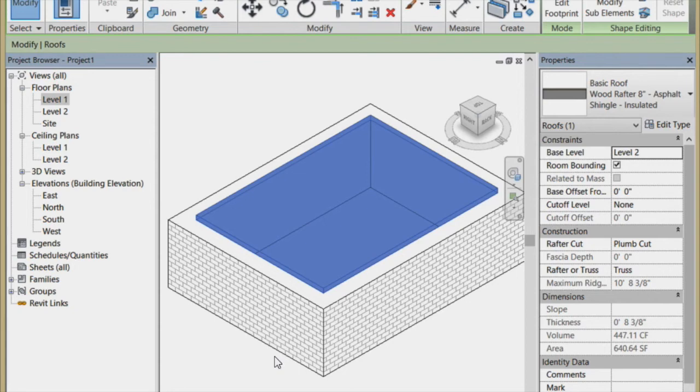The floor is actually considered, in the scheme of things, a relatively good surface area because it's considered inert. So for the most part, it maintains a constant temperature. It's viewed as a very favorable surface. We like the floor, or the earth, because hugging up against the earth, it tends to maintain a fairly constant temperature. We don't lose heat. We don't gain heat through it. It's considered a good surface. The roof can be good or bad because it absorbs an awful lot of solar energy, depending on whether it's a cool roof or not. But that's also a shape that we see an awful lot of, and it tends to be not so bad.